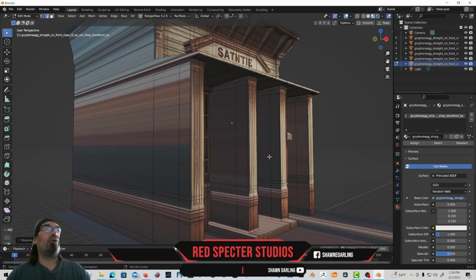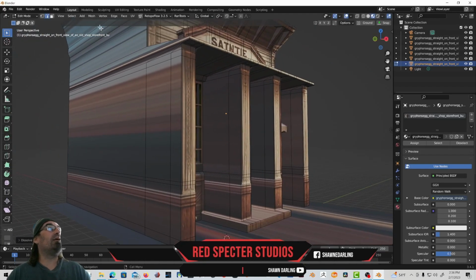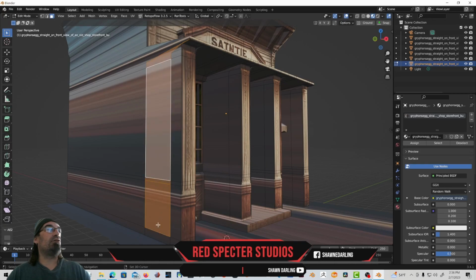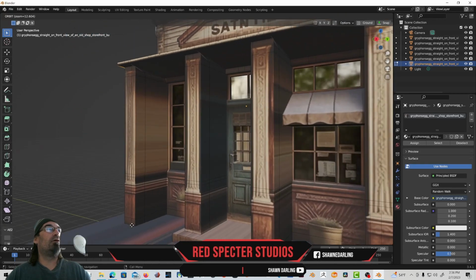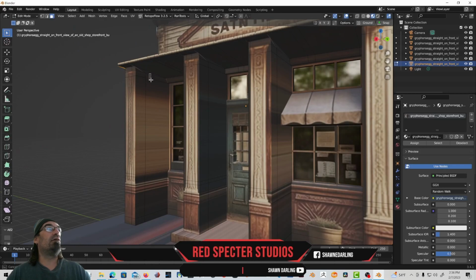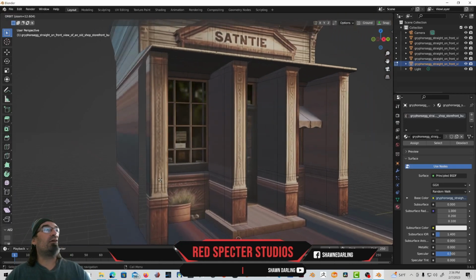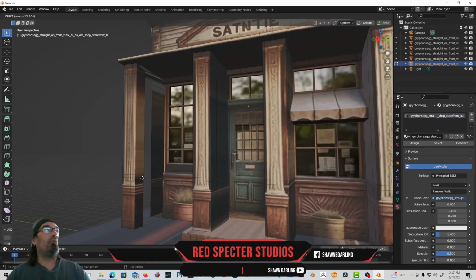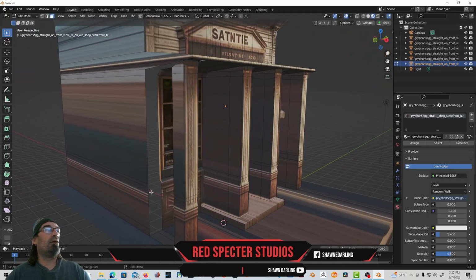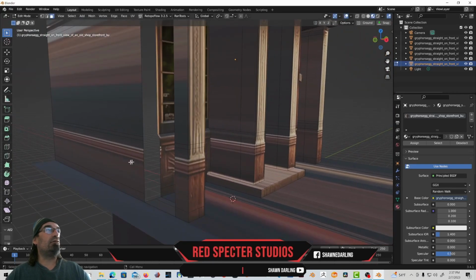Okay, so now we're going to have to do a little bit of polygon building here, and that's real simple by selecting our polygon mode there and selecting all these guys you don't want to exist anymore on both sides here. And we're just going to press delete faces. Pow. We've lost this whole section, and we have to somehow put that back. And that's relatively easy since all of our polygons line up front to back.